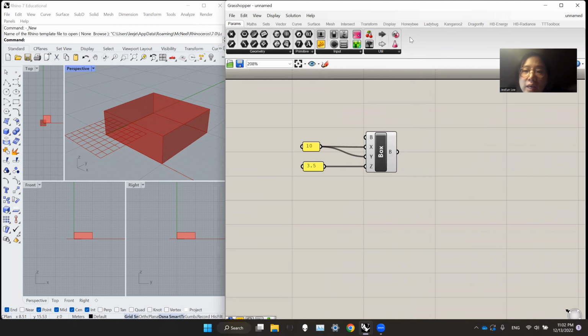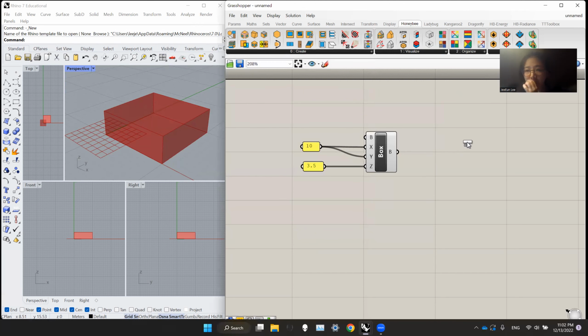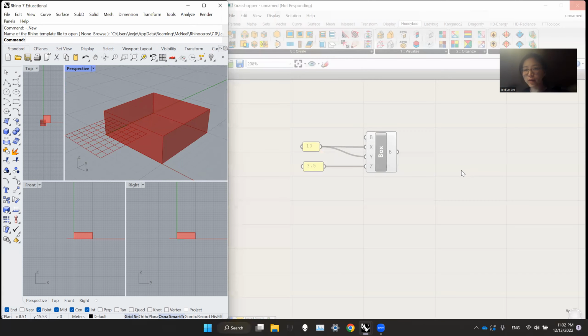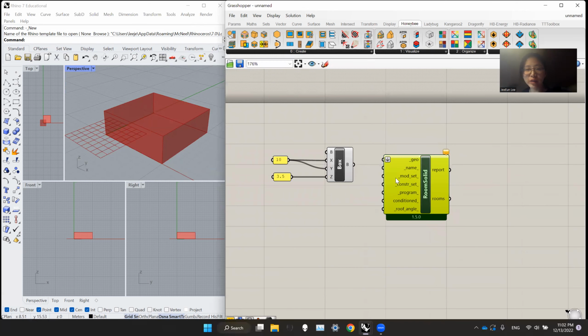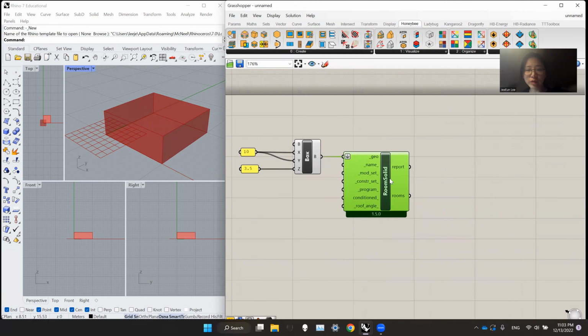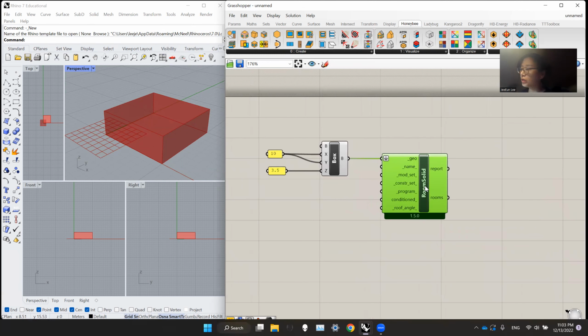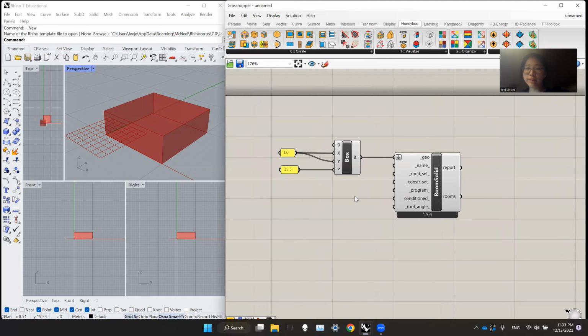And as I always do, I will make a room from solid. Takes a while. Okay, so I will use the box geometry to make the room solid. And so this is the room. And you can also put programs for the room and then use the construction set.